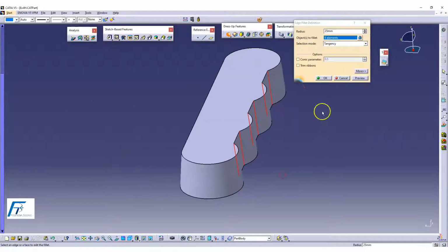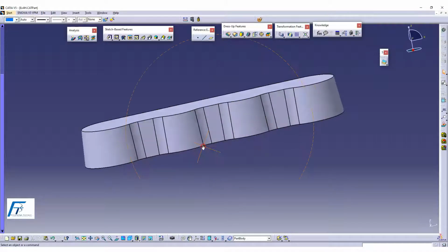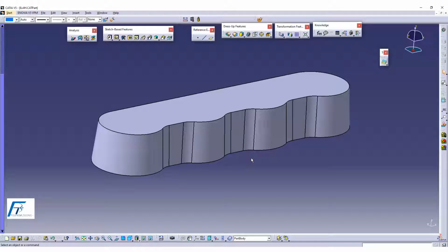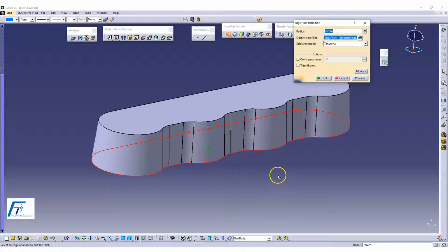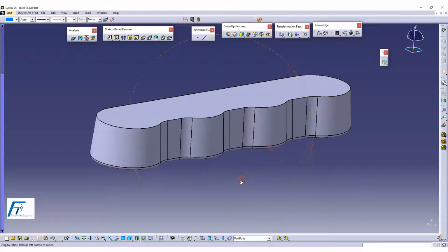These are my vertical edges. I'm going to give the dimension of the vertical edges as 75 mm. The moment I give the vertical edges, it's easy for me to give horizontal edges. The same concept applies here. See this? Give it. Okay, fine. And I'm going to give 10 mm. Right? I just gave this one.